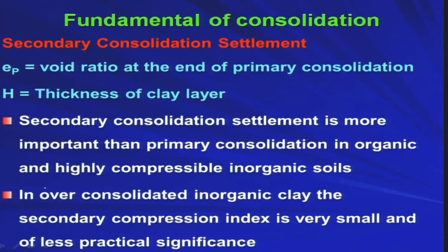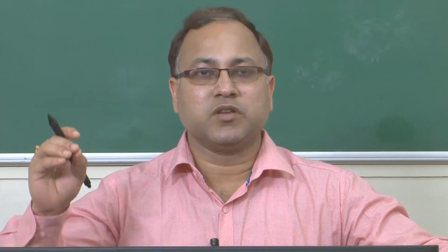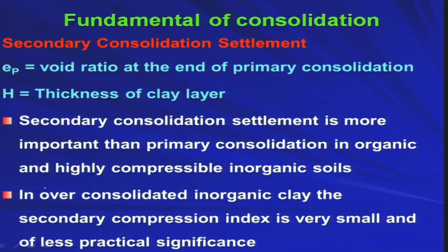So, secondary consolidation settlement is more important than primary consolidation in organic and highly compressible inorganic soils. So, please try to remember, secondary consolidation settlement is more important. Okay. It will be giving you some significant value in case of organic as well as highly compressible inorganic soil. So, the soil which is highly compressible, that means even after the primary consolidation you will be observing some significant amount of secondary consolidation. However, in most of the cases in over consolidated inorganic clay, the secondary compression index is very small and of less practical significance.